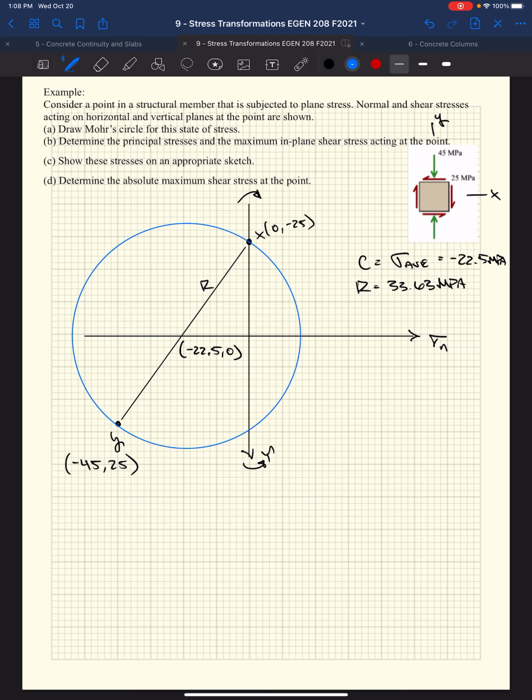So, second to last example here. Again, similar to some of the other examples where we are given an initial stress state, okay? So we're given that we have an orientation of a block, right? Piece of our material or an element. It could be a small block of a plastic rod like this, right? And it's oriented such that this plastic rod has a torsional shear stress on it, right? 25 megapascals, so you could assume if it was part of this rod that it has torque on it. And also it's under compression, right? So we got this compressive load sitting on top of this pipe also, plastic pipe.